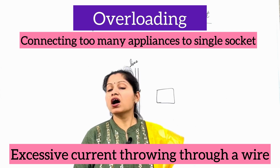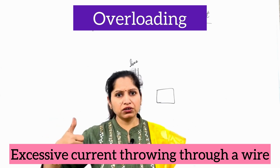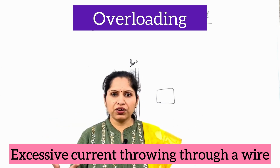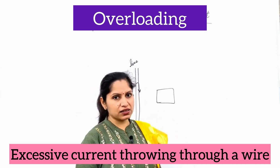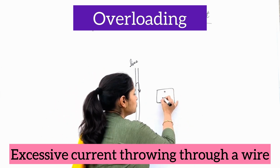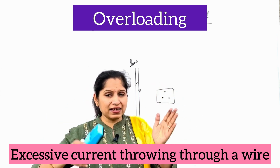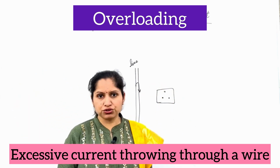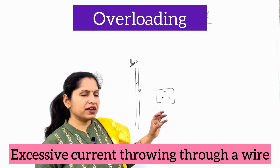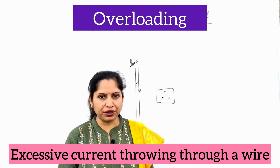So if there are too many appliances connected to a single socket, that is the third reason for overloading. How could you prevent this overloading? You need to check your wiring. That should be proper, that shouldn't be damaged. Second way to prevent overloading is to check that you are not connecting too many appliances to a single socket. The total appliances connected should not exceed the limit of 15 ampere current. It should not be consuming more than 15 ampere current altogether. So too many appliances should not be connected to a single socket. That is another way of preventing overloading.